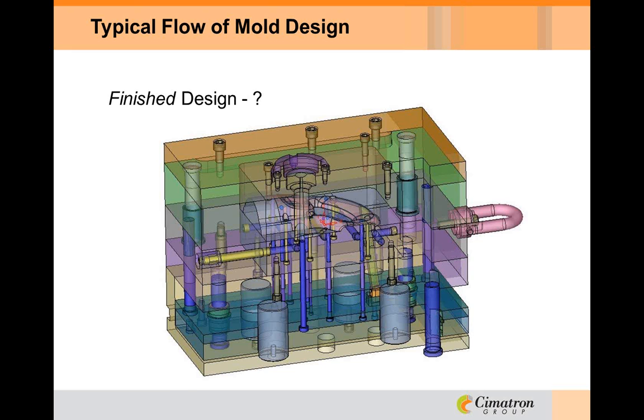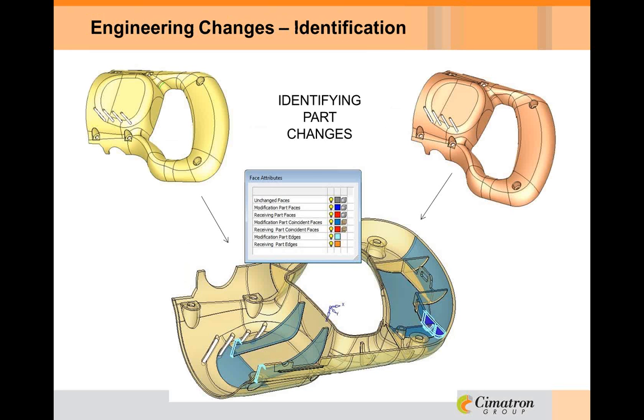That represents a tremendous challenge for the mold designer. In many cases, when the new part data is received, it may not even be clear which areas have been modified. And so the initial task is to compare the latest data to the working model and find every difference. So we'll look at this. A CAD system for tooling has to provide this functionality. Too much is at stake to rely on anything less than a precise overlay of the exact 3D models that are in use.